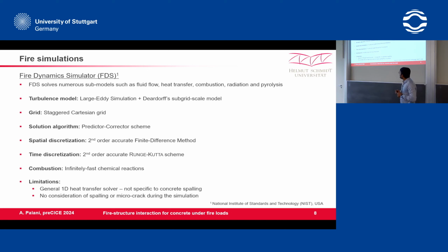of USA, and these are some of the simulation parameters that I use for a general fire simulation. The fire simulation already has the heat transfer equations, but it is limited to only heat transfer in the 1D direction. It doesn't address the extra models that we need, like a crack in the concrete or a hole in the concrete. So that's the reason that we are trying an external structural solver combined with preCICE.